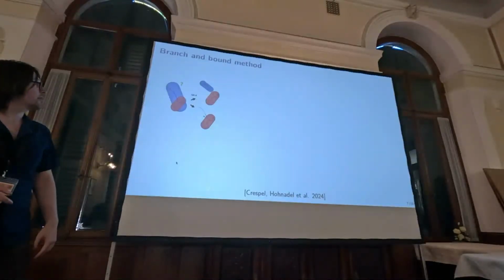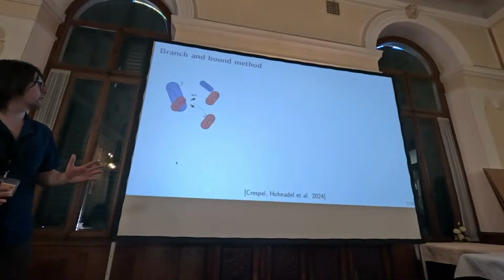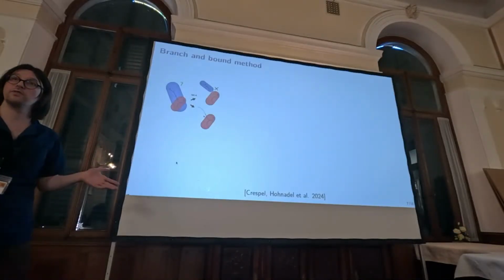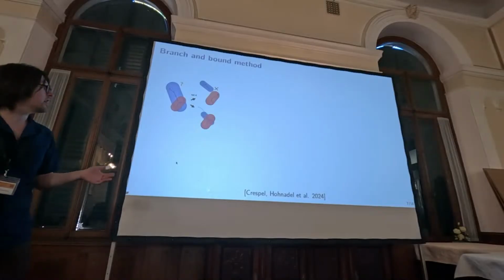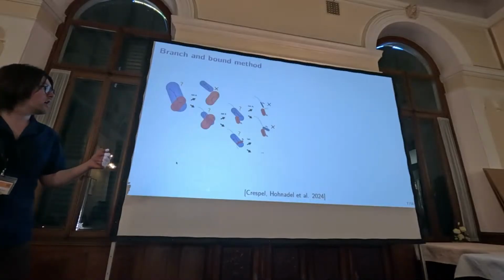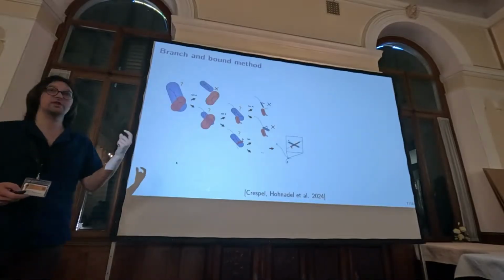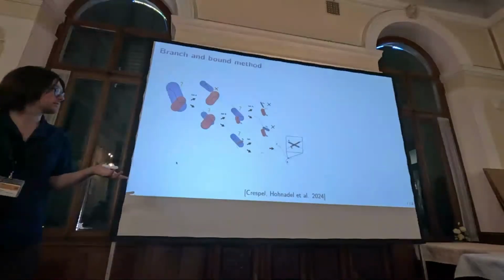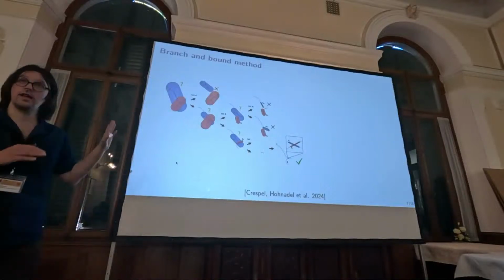We approximate the rods with a bounding volume. If they do not intersect, then we know there won't be any contact, we can stop. If they do intersect, we repeat again and again until either there is no contact or the size of the rod is smaller than a given threshold and we have reached contact. This is a classic approach.